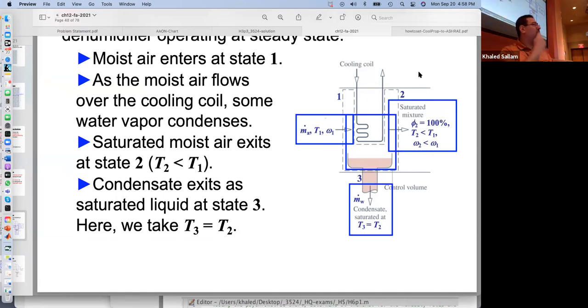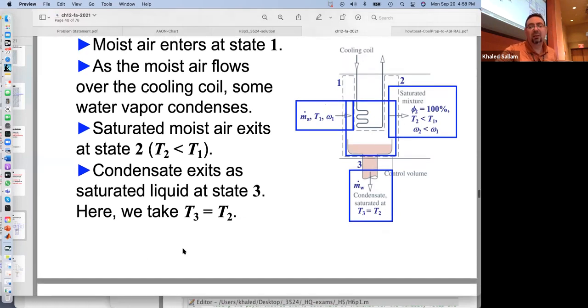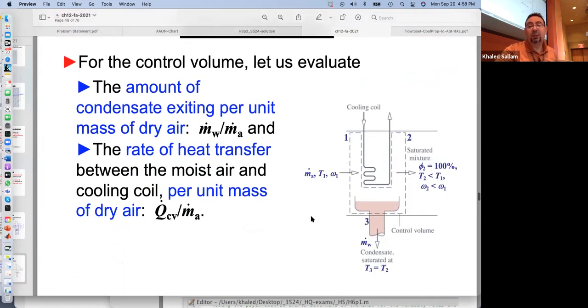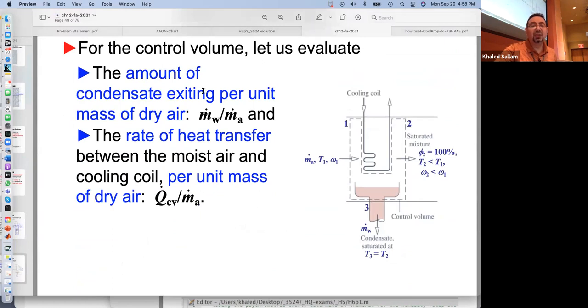See that part, like how much does the water get cooled to? That's heat transfer, not thermal. We're going to go through heat transfer after we finish the thermal part of the course, right? So it has to do with the heat transfer rate and the geometry of the heat exchanger. Okay, very good. So what people basically need from this is to figure out that ratio, m dot water over m dot air, and the q dot over m dot air. How much cooling you need and how much water you'll be able to subtract.